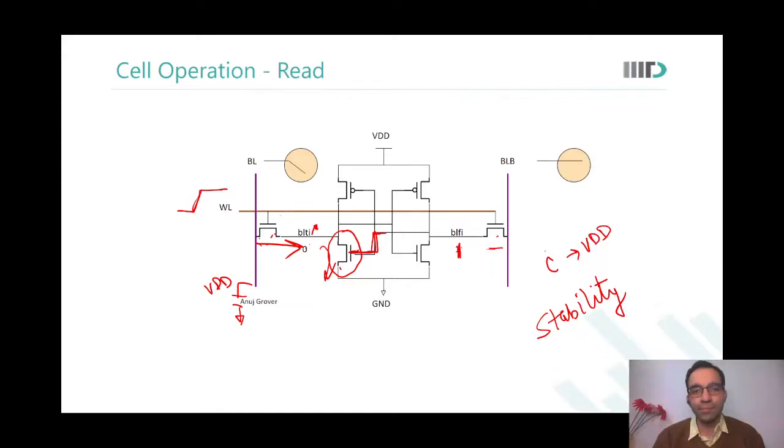Sir, previously we were seeing that our bitline and bitline bar had an inverter in between. So how can they have the same value at the same time? That was a simplistic view for you. As I said, we are going to more and more real views. These are two capacitors, and I can charge those two capacitors to VDD.